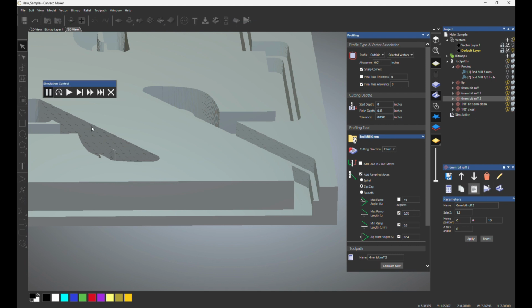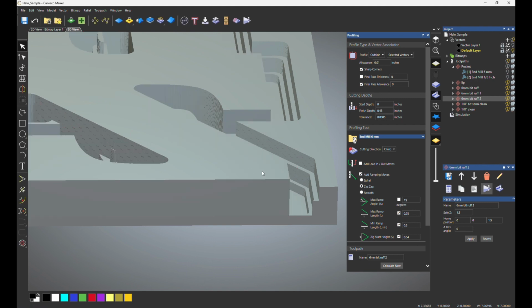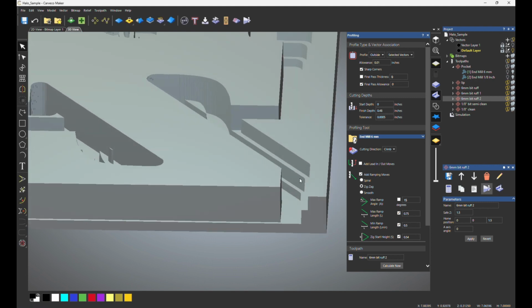We're going to run it again, and it's going to hit, bang, and you see how it now can get all the way to the bottom. And basically you're tricking the machine into treating it like it was a bunch of thinner materials instead of just one thick piece. It's just a tip. You might not need to do it, but if you do find your machine is struggling getting through the thicker material, this is something you can do.